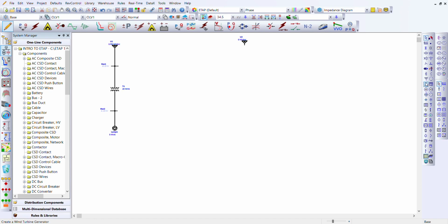Watch carefully. Once I select it, I can no longer select some other components. Why? Because a utility grid cannot connect to them. These are the components that can actually connect to the utility grid, which makes it easier for you to know what can connect to what. Now remember, we are connecting a power grid to a bus bar. Once I click on the bus bar, it will automatically connect due to the Line Autobuild, like this, automatic connection.